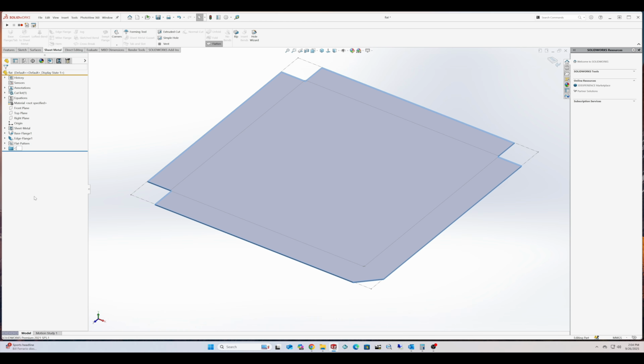If you need it to match the 3D view, if you need it to go in there and show that, now is when you go and create a configuration to where you're going to add those type of radiuses and things in after you're done with that. But you don't have to. If it's just a visual thing and your shop knows that, you're just going to use that machinery, that's how you manipulate the flat pattern. But it's important to understand what we talked about with the peanut butter sandwich. When you're doing these type of things to the flat pattern, they're not going to reflect back to the model.